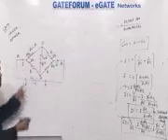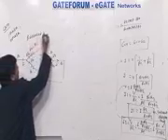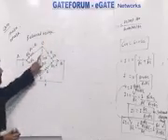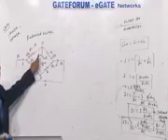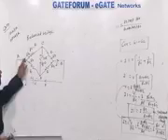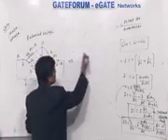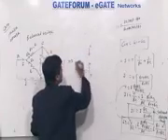That means this is nothing but your balanced bridge. Why is it a balanced bridge? The reason being, whatever these arms are there, they have the same resistance. So no need to apply star delta transformation, because yet we have not come across that. No need to apply any complicated method. We can say that current equal to 0 means this can act as an open circuit in between C point and D point.